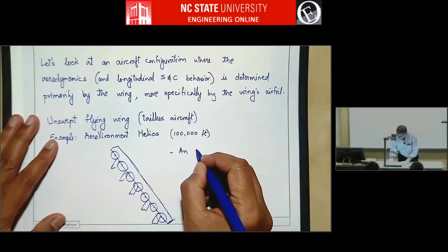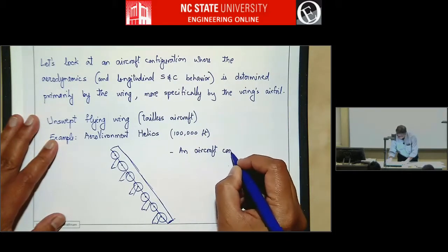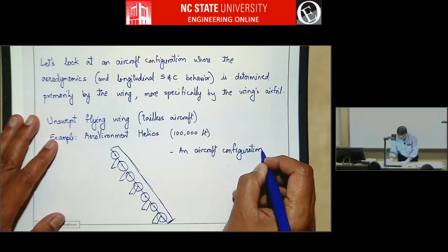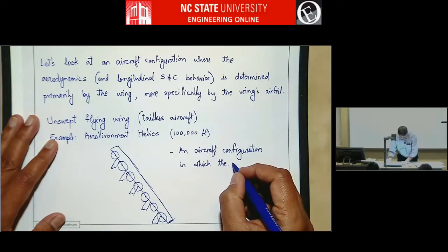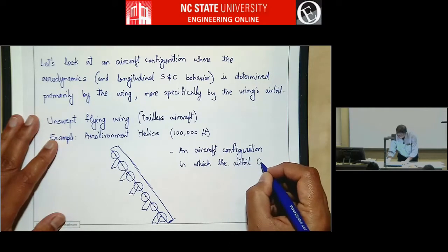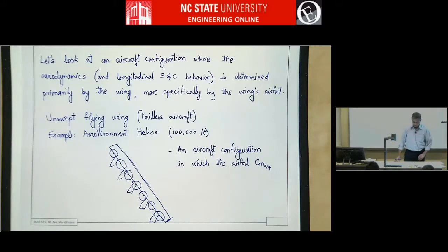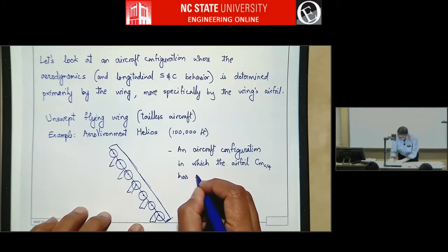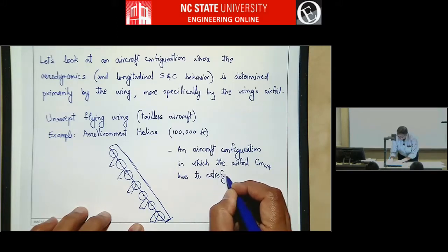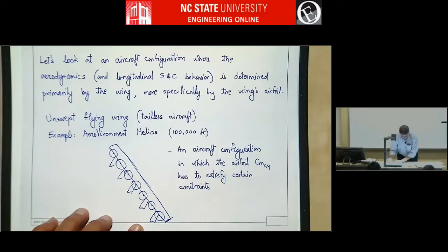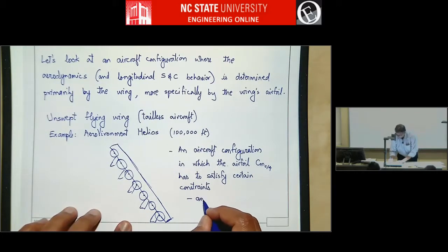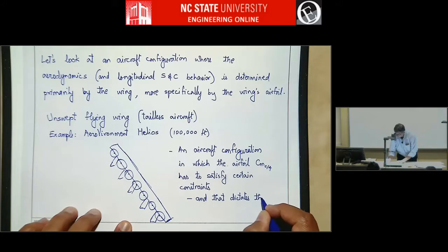And so this is an aircraft configuration in which the airfoil quarter chord pitching moment coefficient has to satisfy certain constraints, and that dictates the airfoil design.